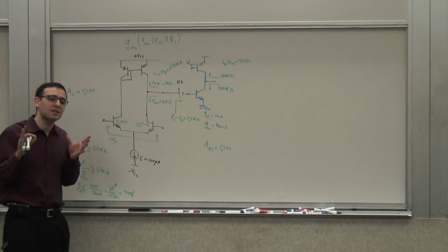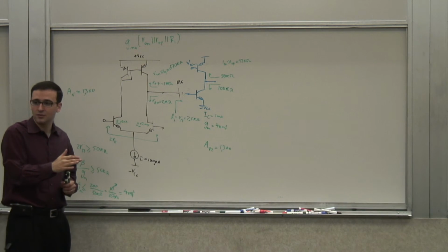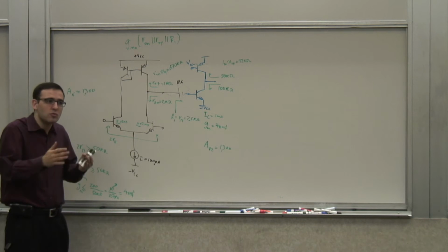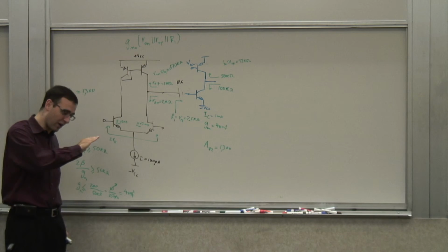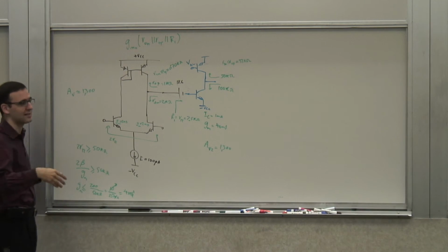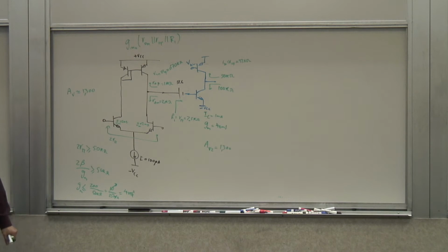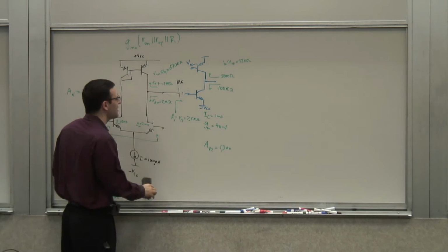Yeah, you can think of certain situations where you have a complete regulator outside that maintains that voltage for you. In those cases, you can assume that, but even the regulator does not guarantee an exactly constant value. There's some fluctuation. Any regulator has a specification of the maximum, plus or minus 5%, something like that. They tell you. So you see the problem, right?